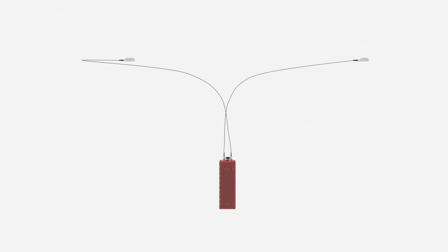Unlike the previous antenna measurements, the product won't improve this measurement in use, so it's important to measure as accurately as possible. The measurement needs to be accurate to within 5 centimeters. Take care to measure from the center of one antenna to the center of the other. The separation of the antennas should be somewhere between 1 and 5 meters.